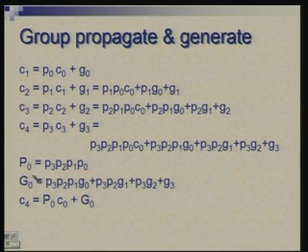This is the propagation condition across 4 stages. G0 is the generation condition in these 4 bits. Generation takes place either at stage 3, stage 2, stage 1 or stage 0. Generation may take place at any of these 4 stages and propagate out to the extreme left.